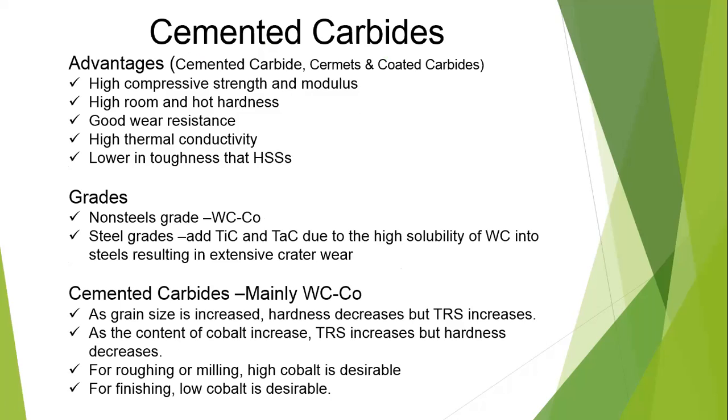Cemented carbides, cermets, and coated carbides. There are some advantages of this type of cutting tool: high compressive strength and modulus, high room and hot hardness, good wear resistance, and high thermal conductivity, but lower toughness than high speed steel.